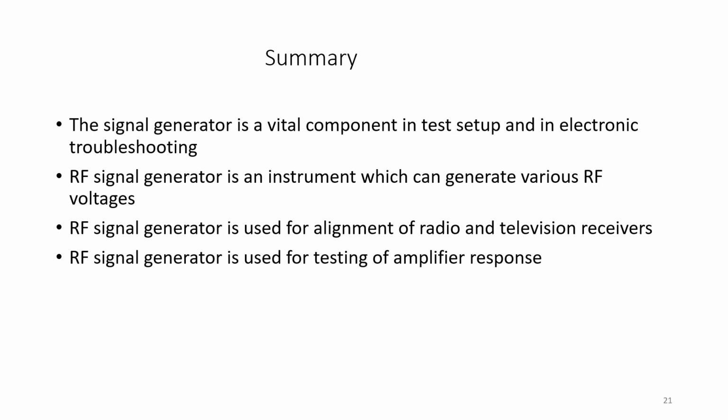To prevent one component from affecting another through their common electric or magnetic fields, we do what is called shielding. If proper magnetic shielding is not provided to the main oscillator of the signal generator, then there will be chances of interference due to the radiation from the wires in the system. This interference will affect the nearby equipment. So the radiation field effects are eliminated by using RF shielding in RF signal generators.